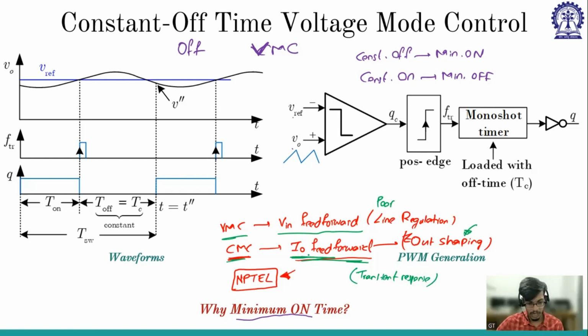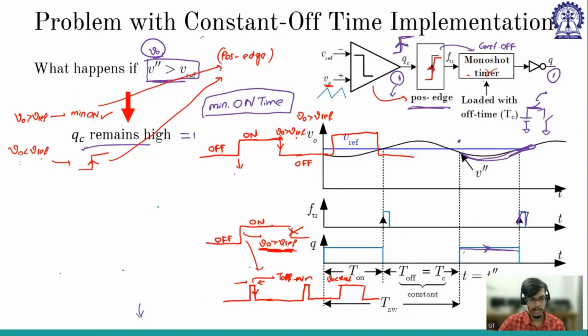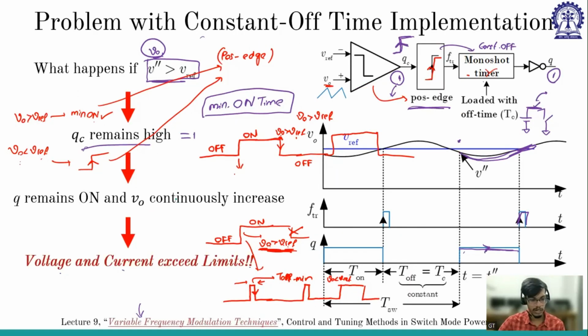But for load current feed forward, we have to sense the load current. So you have to have the provision of load current sensing, and only then can you use load current feed forward. Without load current feed forward we can also have a good transient response, but in its presence the transient response will be superior and much faster. There is less than a minute left, so if this meeting ends, please join in so we can continue our discussion.